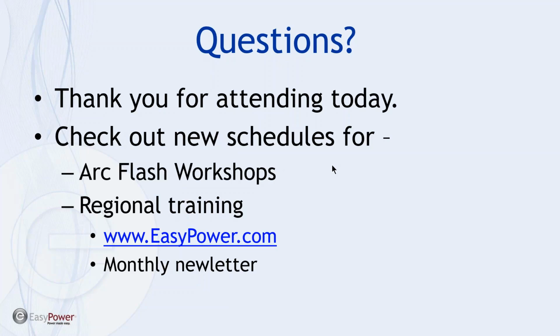Okay, the question is, is there a reason to use momentary current? In fact, it shouldn't change anything. Integrated method in EasyPower takes the half cycle current and applies it to the first cycle of the fault. At that point, if the fault lasts longer than a cycle, for the next 8 cycles it uses the 5-cycle current. And then if the fault lasts longer than that, it uses the 30-cycle current in the integration.